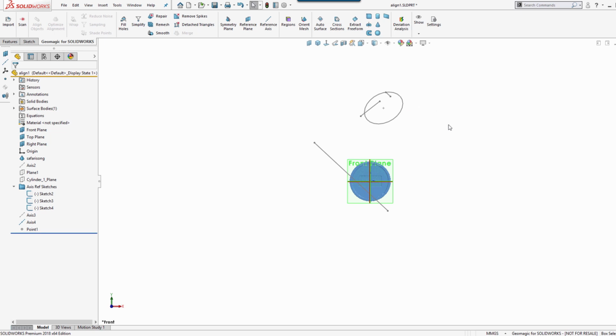Now that's true whether I'm in the SOLIDWORKS add-in or I'm just in the Design X package. Really, a standard thing to do is make some sketch geometry or even axes. And once you use them, you frankly don't need them anymore, probably, so you can get rid of that stuff. You definitely don't need the sketches and whatnot that are way off in space because they don't move with you. They're kind of trash at that point, and there's no reason to keep those in your model.